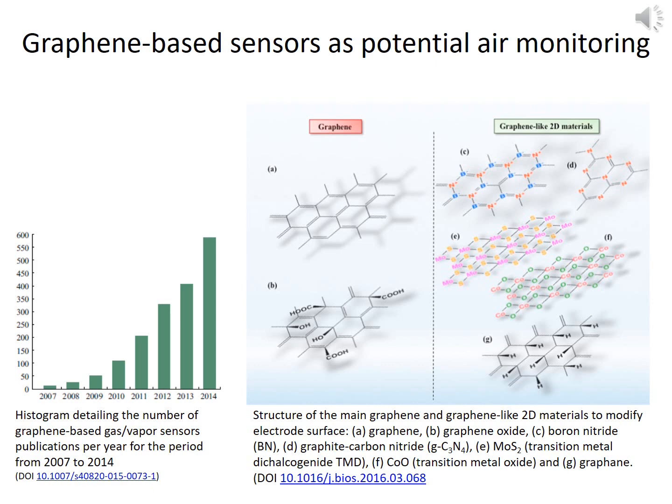The combination of graphene-zinc oxide hybrids and reduced graphene oxide was already used to develop high-efficiency gas sensors. Palladium-decorated graphene was able to detect hydrogen in the concentration range of 25 to 10,000 ppm. This sensor showed high sensitivity, fast response and recovery, allowing use over multiple cycles.